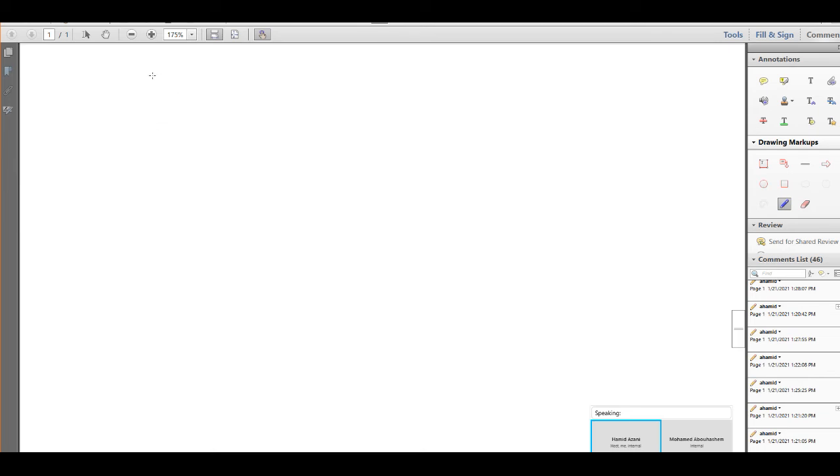But look, the diode in general, that's let's say the electrical symbol for the diode, but inside it has a small battery like this, and that's the diode like that. Now, once you use the physical diode, the real one, that diode will be conducting once the input voltage is bigger than this internal voltage, and we call this a threshold voltage value.